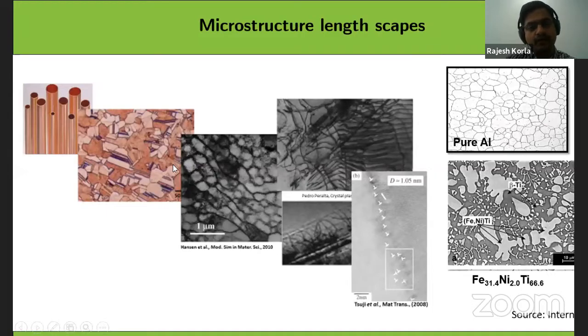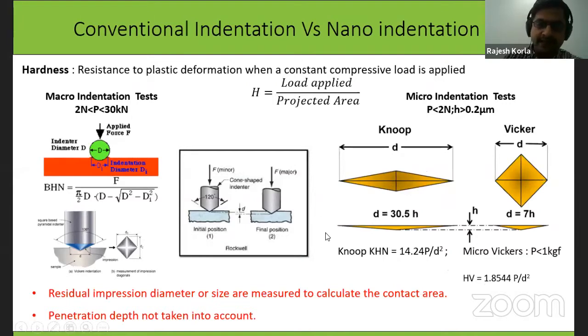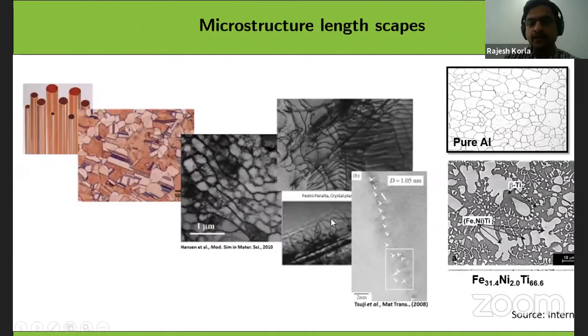And in the TEM you see the dislocations, and how they move along a particular direction. These are the grain boundaries, and the dislocations come there and pile up ahead of the grain boundary. If you go to further magnification in TEM, you see the HRTEM. Here each white contrast dot represents an atom. It is not strictly one-to-one, but each white contrast can be considered the representation of one atom.